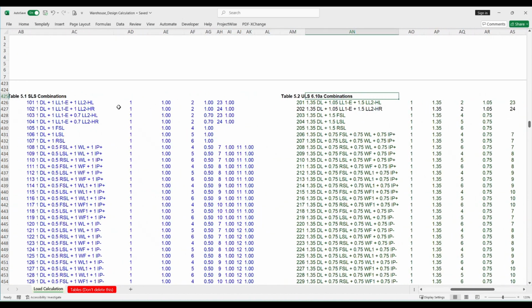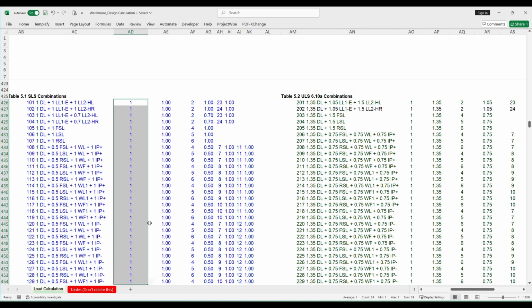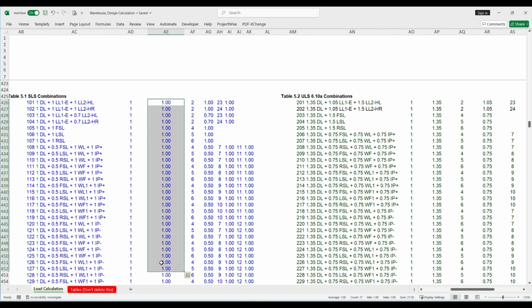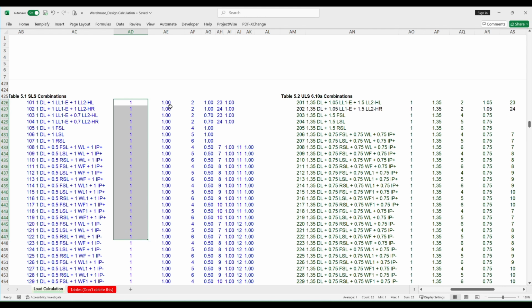and this column is the load case, the first one, that is the permanent load, and these are the factors which are applied with respect to the load combination factors. The first case is self weight, and the second column is about the factors which are to be multiplied for the self weight, and this one is a leading variable, and these are the factors which are to be multiplied with that, and finally this is an accompanying variable or leading variable.